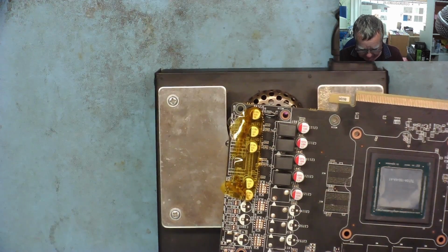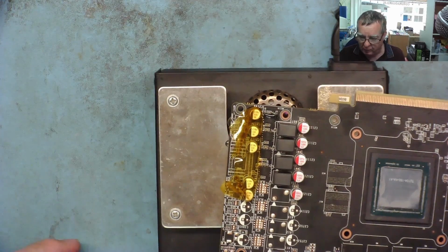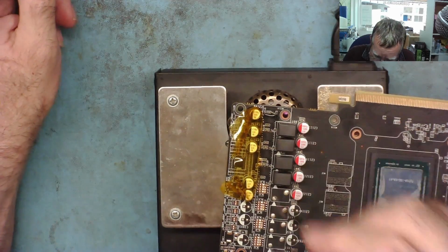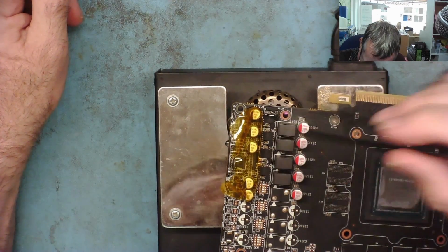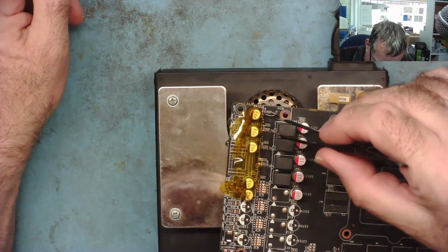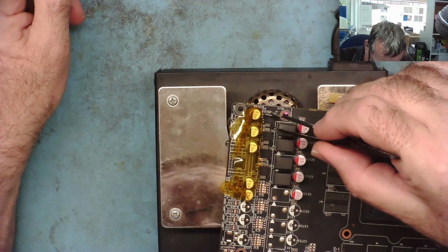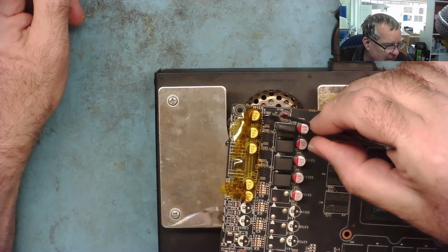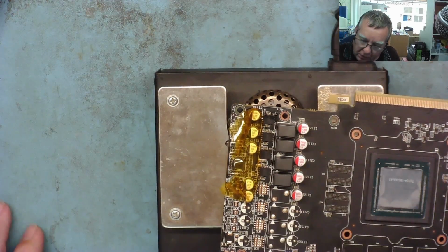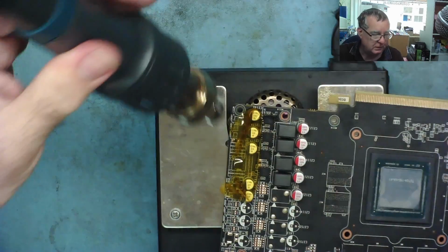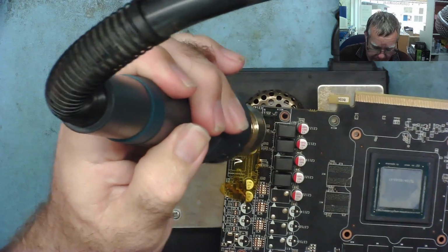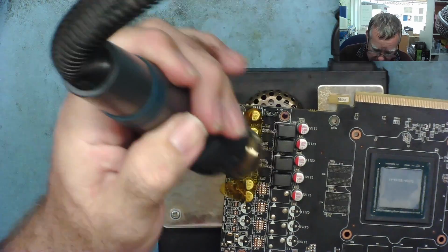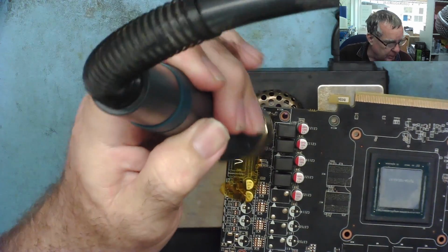I'm now going to turn the preheater up to full. I'm going to try to do this right-handed, which is a bit awkward because the brackets here and I might actually burn the back of my wrist. Yeah, I can get it from this direction. Let's get the hot air. So hot air on 450 degrees maximum airflow using the quick 861DW, and I'm now going to try and remove this.